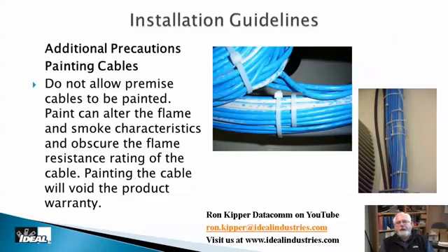So there's a lot of different ways of making sure you're managing that cable bundle properly and not damaging it in the process. Now, as I said earlier, make sure your cables are never exposed, because one main thing that happens to them over time, it's going to happen, is they're going to get painted. And when those cables get painted, that basically ruins any fire rating on them and any warranty you might have gotten from a manufacturer out there on the cable installation.